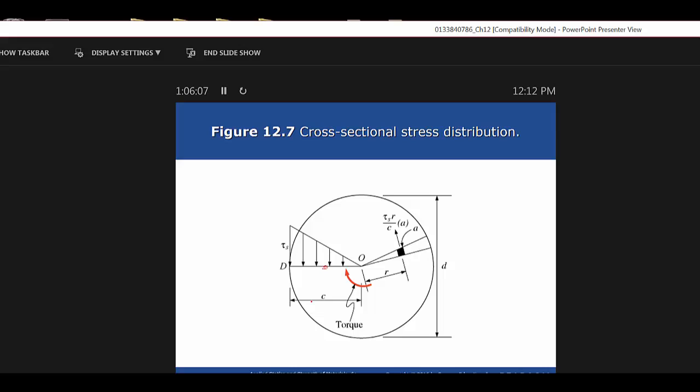So we punched those numbers in, and we should find out that max shear stress is 7,570 pounds per square inch. So that would be a number we'd have to go back and make sure that we were below what that would be for that material. Now the second part of that, you've got a hollow shaft, and the outside diameter is 4, the inside diameter is 2. So again, polar moment of inertia, just take that outside number of 4 to the fourth power minus the 2, which is the inner diameter, to the fourth power, multiply that by pi, and then divide the whole thing by 32.